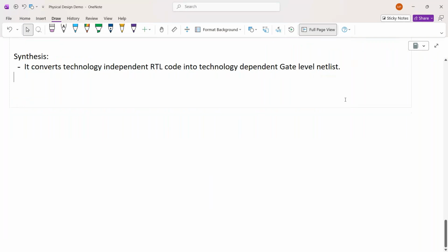So you will find after the synthesis, it converts that logic. Now the logic is there, which is technology independent. It will convert that into technology dependent files. Now you will see here, you will not see any if statement, else statement. No complex things will be there because your synthesis tool has worked on it properly, right? It has replaced those if statements, all the behavioral code, into some logic, right? So it has replaced it with AND gate, OR gate, NOR gate, or all those things, right?